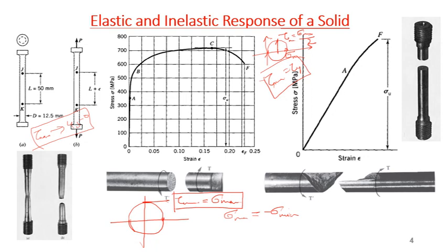Now, what does this mean? If the maximum stress is the yield strength, then tau y will be exceeded, because we know from the uniaxial case with load sigma y that sigma y is 2 times tau y, or tau y is equal to sigma y by 2. This is the material property, and in this case that cannot be possible, right? So when the loading condition changes, for the uniaxial state of stress, it's not any problem.